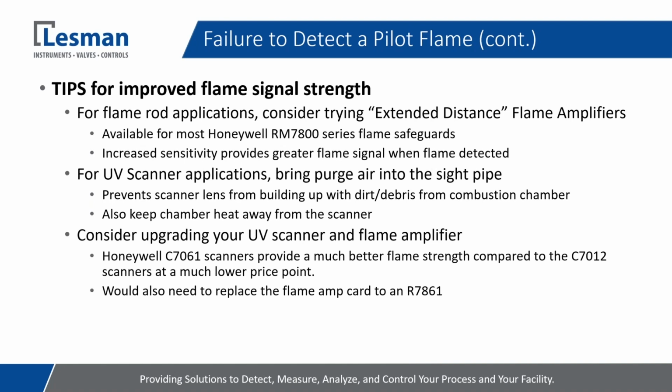So a couple of tips that I've come across that I would recommend to people having problems with the detection of pilot flame. Honeywell has what they call extended distance flame amplifiers. You may see a little footnote saying for distances over 50 feet, use this model number. I have used that on applications where the distance is considerably less, and it's made a huge difference in the flame signal strength and the reliability and repeatability of that application.